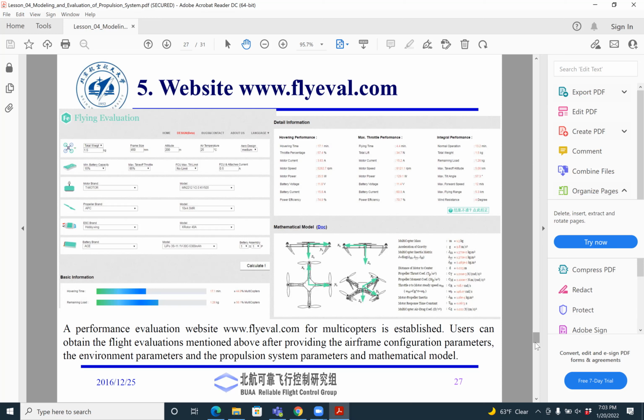So if you get a chance, go on to my YouTube videos. We designed a quadcopter gripper wherein the dynamics of the gripper was decoupled from the dynamics of the quadcopter. You would see that there's a quadcopter, there's a counterweight, and it is grabbing that microplate. You will notice that the instability actually counterbalances that microplate, but the quadcopter is stable. So basically it is decoupled. So there are techniques to decouple the sling load from the quadcopter.